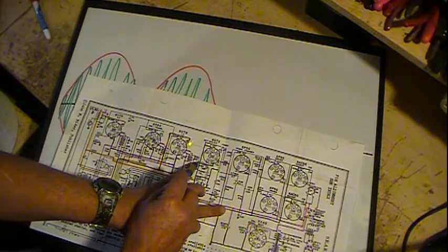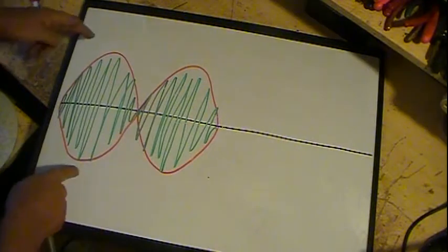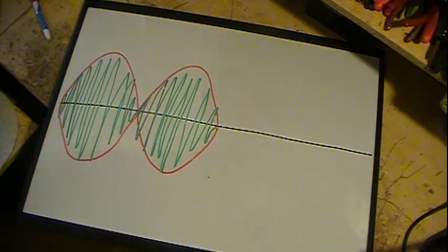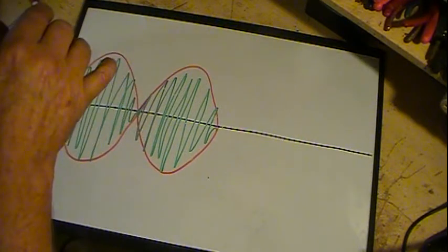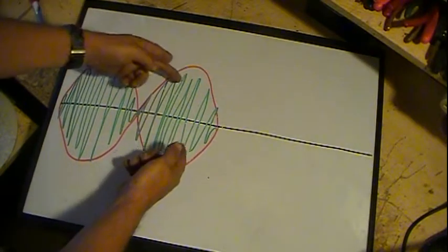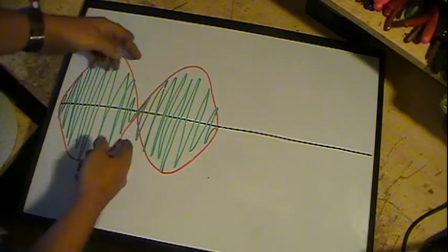Now, what comes into our detector tube, coming right out of the output of the second IF, will be this signal. You'll see this, and it'll just continue on. Now, that's all fine and dandy. The only problem with this is I can't do anything with it. The red is the audio portion of this RF that's in there. The green is the 455 kilocycles, and the red will be our audio.